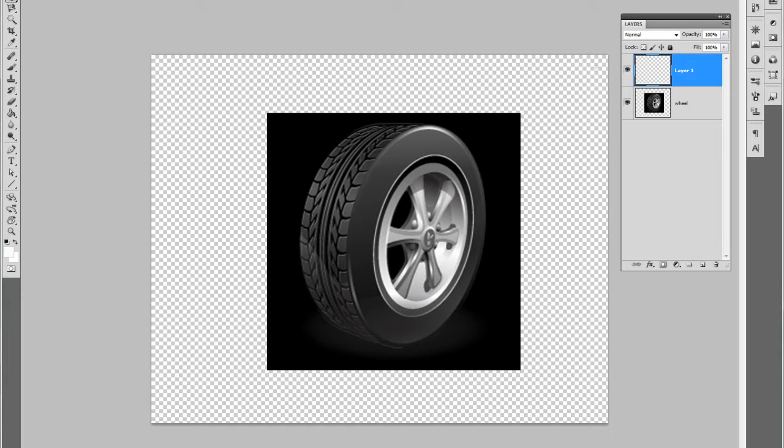I'm going to do it again. I'm going to select and go down. I have that selection. I'm going to add to this selection by hitting shift and then go outside of that selection. I'm going to hit shift and go outside of that selection again. You notice how it's adding, right? As long as I hit shift and select, it keeps adding. Now I'm going to hit alt. Now watch what happens. It takes away. So just remember shift and add.